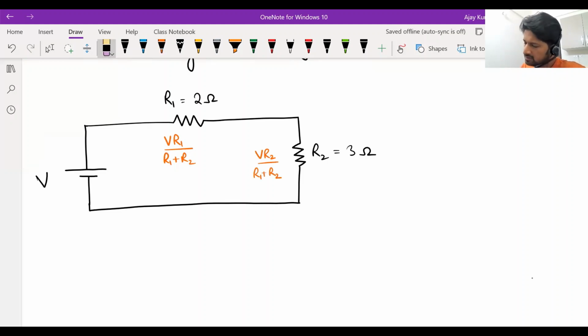Okay. Suppose this resistor R2 is a load resistor. Fine. So it's the resistance inside some device. And assume that device can only withstand voltages up to say 20 volts, not more than that. Okay. So let's mark these points as X and Y. The potential difference between X and Y should be less than or equal to 20.